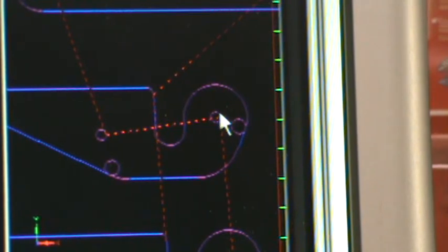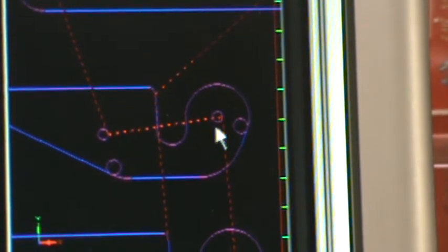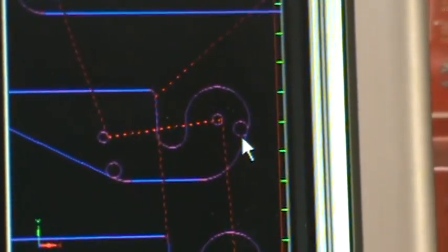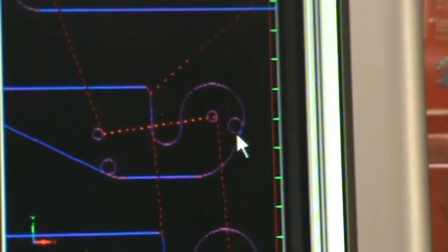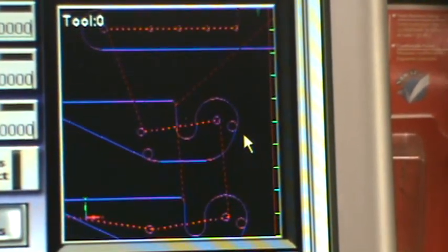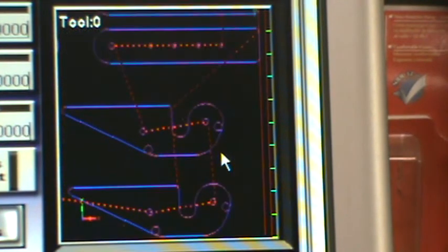So if you have a hole here that's about the size for a 440 bolt, and then you do this hole here, it's going to cut into that hole for that 440 bolt, and then you're going to be all messed up, and the parts are going to be worthless.